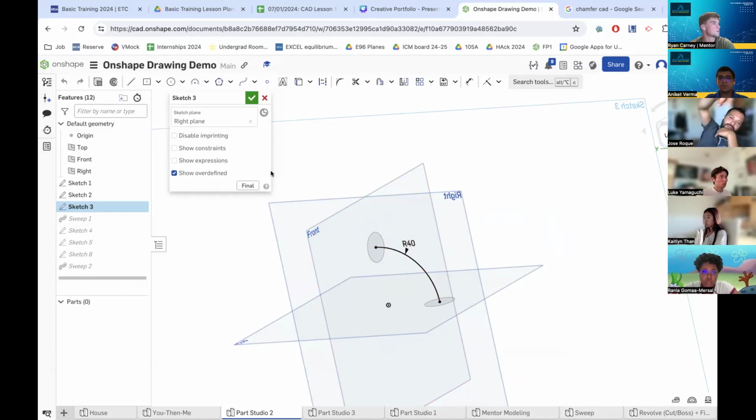So the path, you have to create a path between planes so you can do the extrude, revolve, or whichever you want to use. For the sweep, you have to define a path in between the two points. That's how it'll know to sweep along that path. And the two points or shapes, two planes or whatever, right?